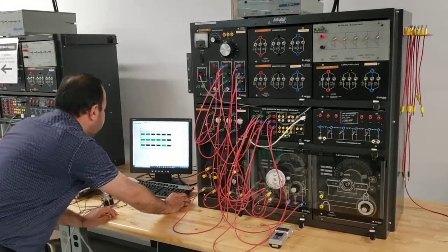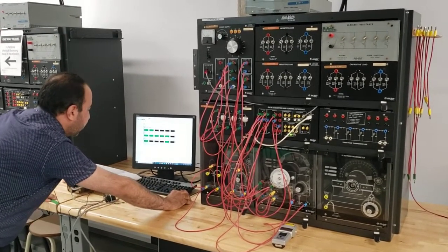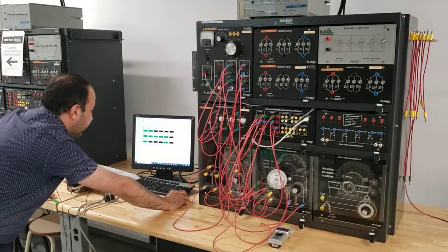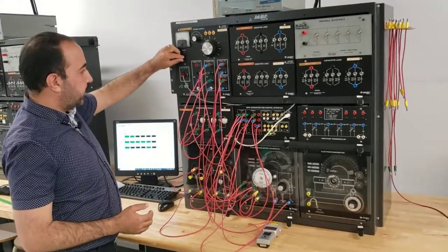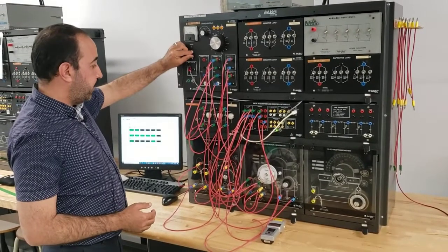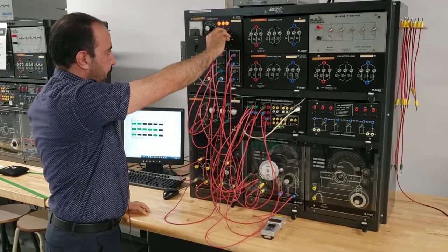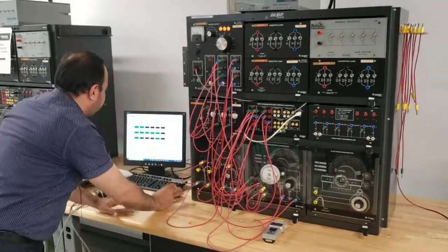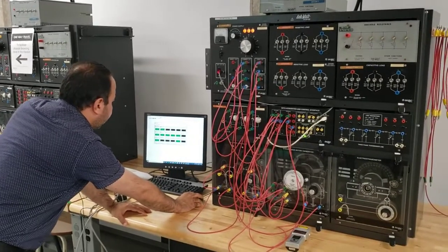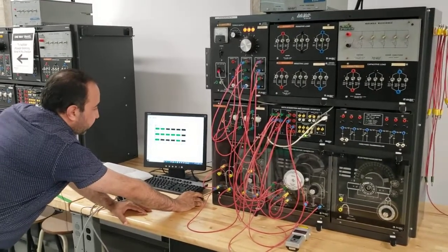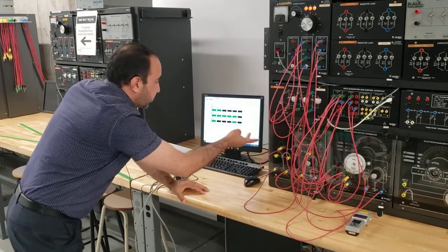I would like also to measure the power between E1 and I1, so I adjusted this guy for the power. It could be measured active, reactive, or S. I will measure the active, and then I'll see. So what I need right now, I will try to see the synchronous generator, and I will try to see my readings here. I'm seeing negative sign here because of the connection of the ammeter. This is DC. I can switch between them.